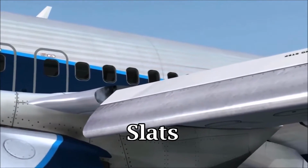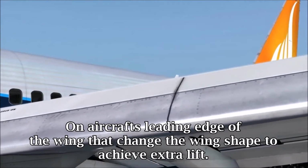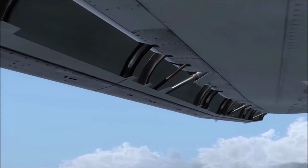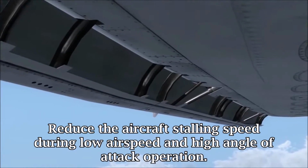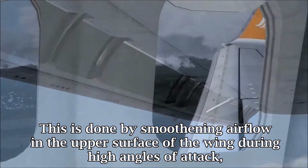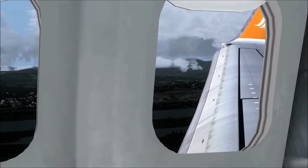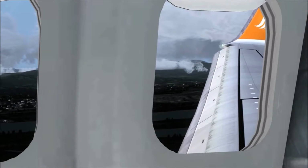Slats also are movable devices on the aircraft's leading edge of the wing that change the wing shape to achieve extra lift. They commonly extend forward of the wing's leading edge. Slats are also available to reduce the aircraft's stalling speed during low airspeed and high angle of attack operation. This is done by smoothing airflow on the upper surface of the wing during high angles of attack, therefore generating more lift. Angle of attack is defined as the acute angle between the wing chord line and the relative wind.